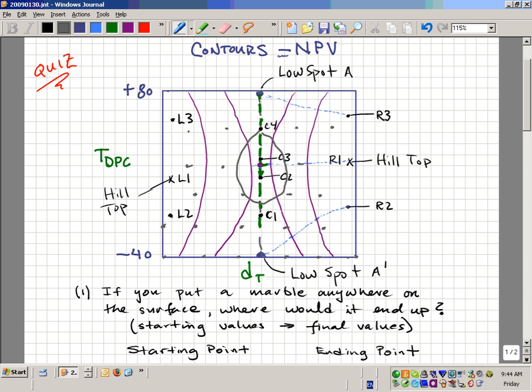But in 10 years, this could become the hub of a new processing facility that not only this field comes into, but that you provide, there's some other satellites around. They're not going to be able to afford to put in a dew point controller on their system because it's not big enough field. But we can take their gas, we can buy their 10 mole% of gas, convert it to liquid, make more money off of it. Okay? We'll buy their gas, strip out what we can make more money on, so it can become a potential money maker into the future. You see what I'm saying? Or not?